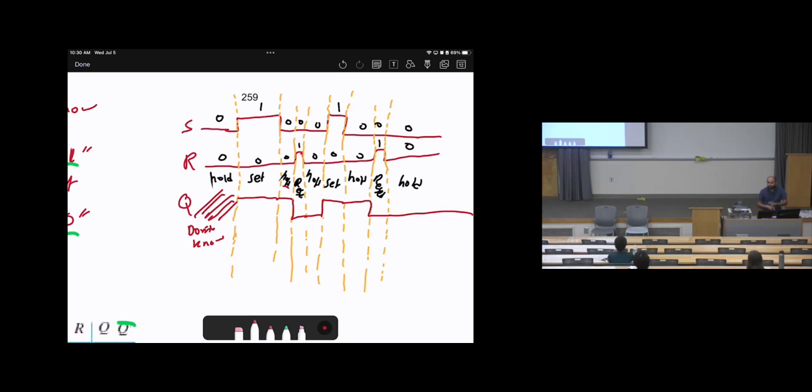So whenever we deal with a timing table, the first step, look at the changes, make guidelines for the changes. The second step, put zeros and ones values. Then third step, determine the mode: hold, set, reset. After that, you can draw. Then it will be much easier.